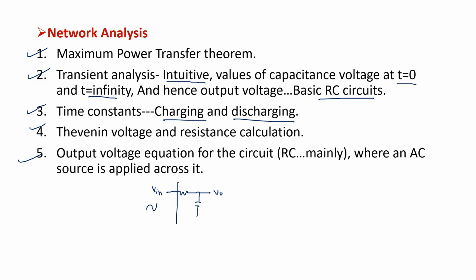So this in-between circuit has some transfer function. On the basis of the transfer function, when we replace its frequency with the input signal frequency, you will get some phase and magnitude, and according to that phase and magnitude we have this output V out. I think these things are usually asked in GATE, so you people should have the idea. So this is some kind of AC analysis where we apply an AC input across some circuit, and its transfer function is used for the magnitude and phase plot of the output.